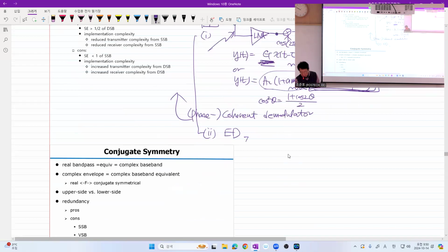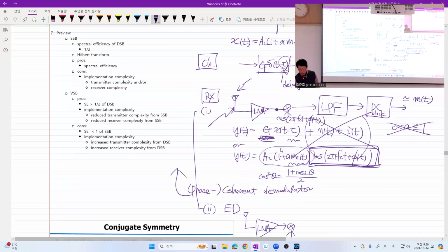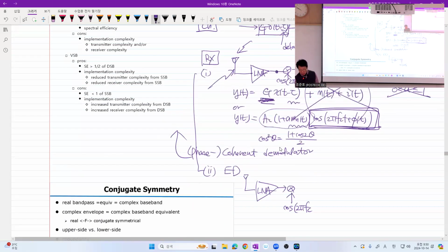What you do is, instead of finding and generating the exact demodulation carrier that is the same as this factor, you do your best to generate one that has a very close carrier component, so that every other phase noise can be put into another time-varying function, theta of t.